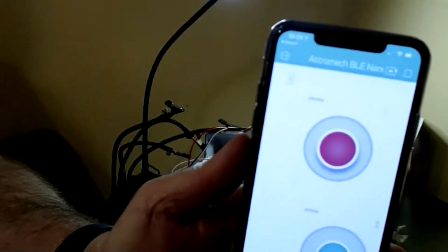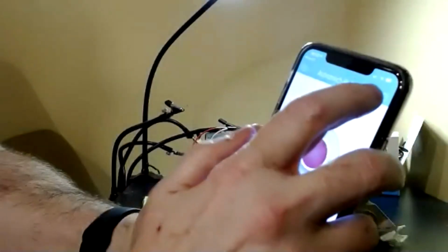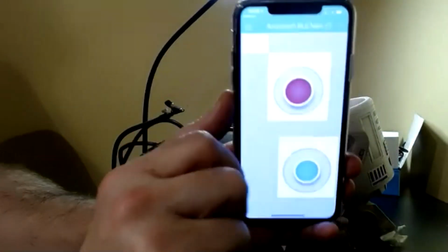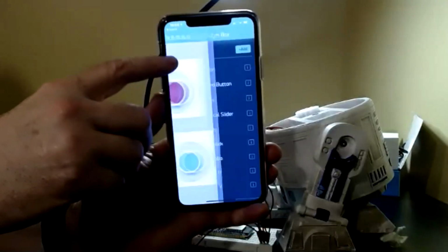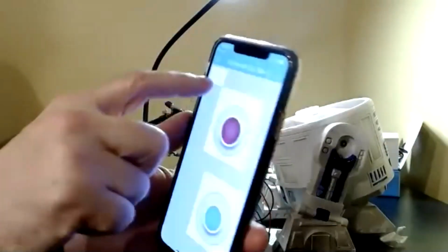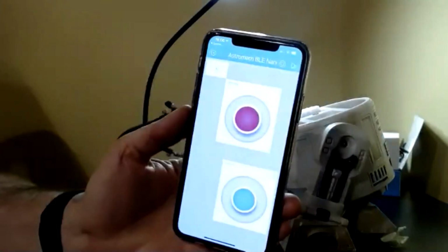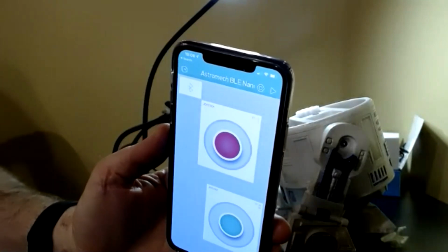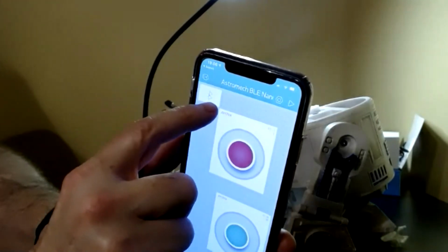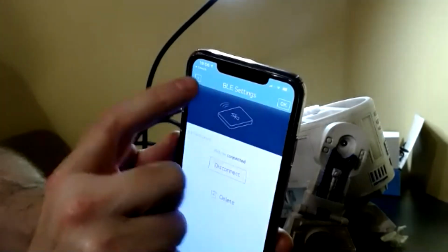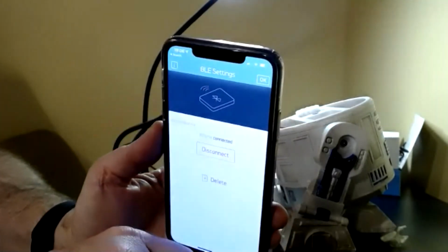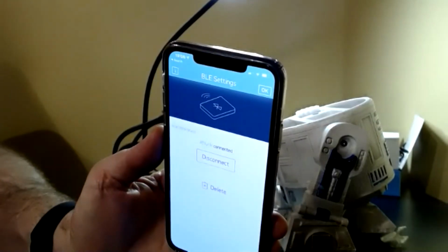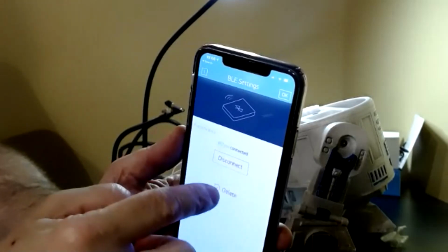So I've got everything up and running and working as it said, but I couldn't work out how it connected. And the reason is that on the Blynk app there's a little symbol at the top, which is a Bluetooth button. As well as the joystick, there are little widgets that you can put on there, and you put this little Bluetooth button on. What the Bluetooth button does is when you press it, it takes you into the connect screen. Without that, I couldn't work out how to connect the thing to the Bluetooth. It just wouldn't connect.